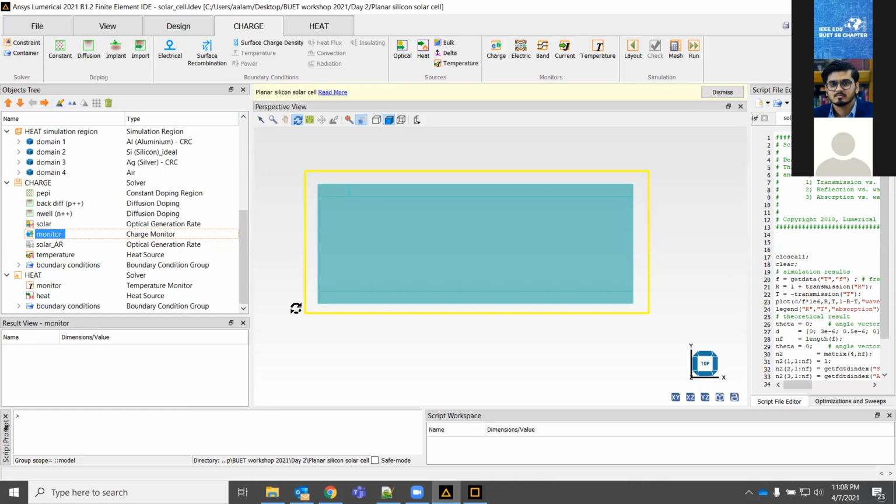However, within the solar spectrum, you absorb a lot of photons that have energy much higher than the band gap of silicon. When you absorb these photons and they generate an electron hole pair, only part of the energy of the photon is used up in creating that electron hole pair. And the rest of the energy is used up as thermal energy.